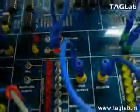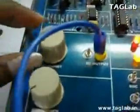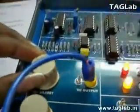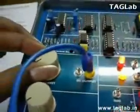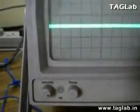Now, after making the connections, switch on the kit. The power LED is on. Now here, we have adjusted the signal at plus 5 volt. When we move the knob, the signal is measured from minus 5 to plus 5 volt. Now the signal is at maximum, plus 5 volt.